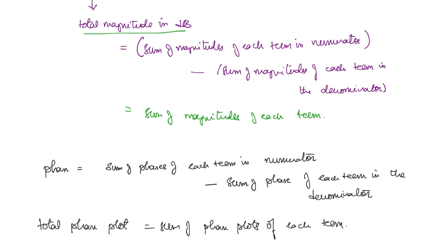So what we will do now is take a simple function and find the magnitude and phase plots of that function, and then we will take the example of a function having multiple terms, and then we can construct the Bode plot of that function. First we will take a real constant, that is, it does not have any imaginary part. Let us say that function is k, so g of j omega is equal to k.